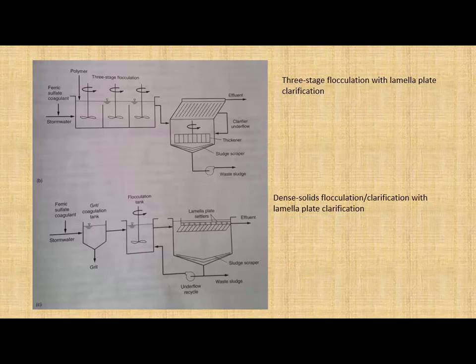The influent wastewater enters an air mixer zone where grit separation occurs and the coagulant is injected. After mixing, the wastewater flows into the first stage of a two-stage flocculation tank, where polymer is added together with the chemically conditioned recycled solids.